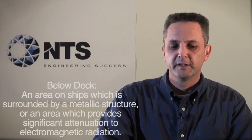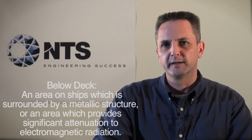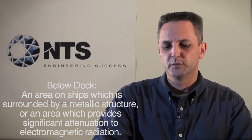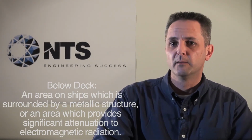Below deck is an area on the ship which is surrounded by a metallic structure or an area which provides significant attenuation to electromagnetic radiation, such as the metal hull or superstructure of that ship, the pressure hull of a submarine, or screen rooms on a non-metallic ship. Although these are on the same platform, they will have substantially different electromagnetic environments. So it's important to determine the difference between above decks and below decks platform criteria.